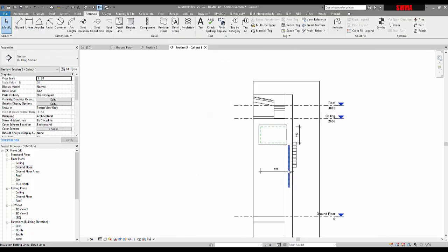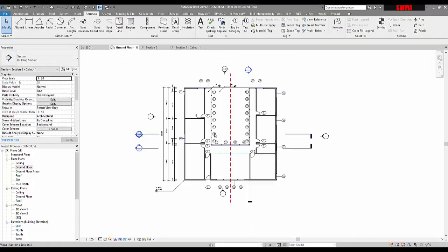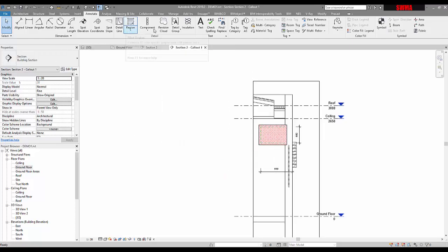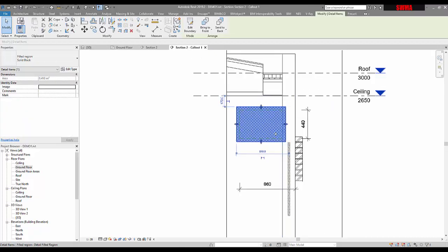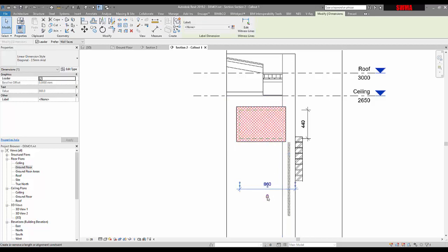So nice and simple. So that was a quick intro to dimensioning, and just touching on how you can use some of these detail tools to work up your extra annotation information inside of Revit without having to do everything in 3D, and then locking, again, using the dimensions to have it track with that wall as it moves around.